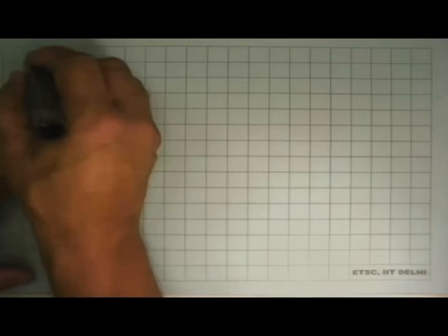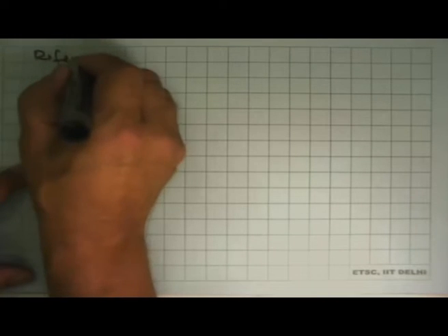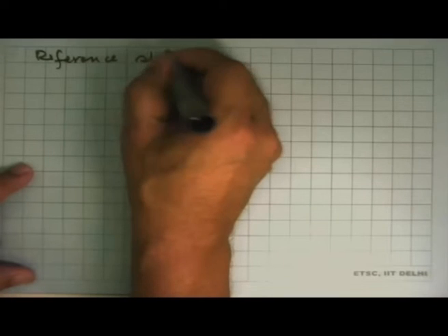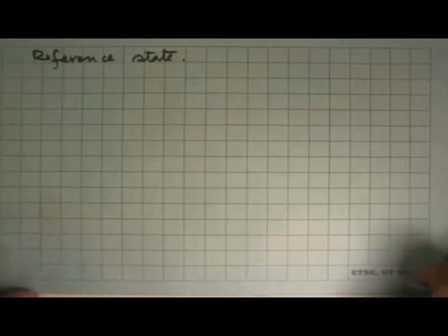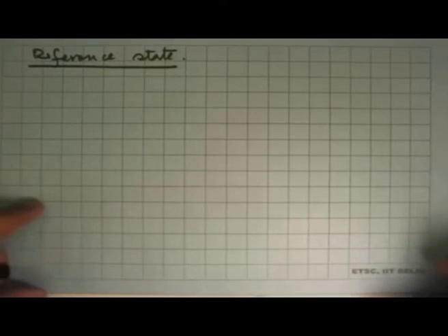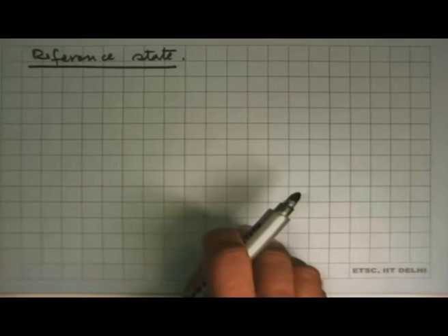Okay, there are questions. We will take questions. Well, there's just a few more points that I need to make. In making the properties and putting numbers, we need a reference state. What has been done over the past many years is that we select a state so that values of U, H, S and all, they are somewhat nice, manageable numbers, and it's not that all of the numbers are 10,000, 15,000, 20,000. So different materials have a different reference state.